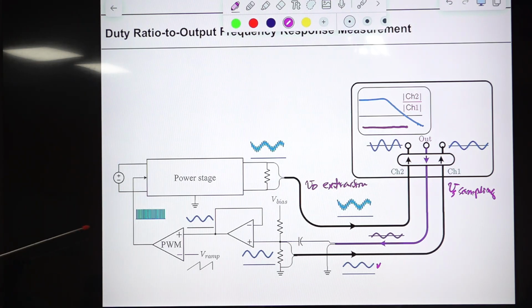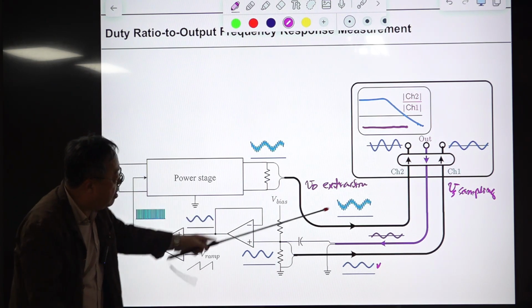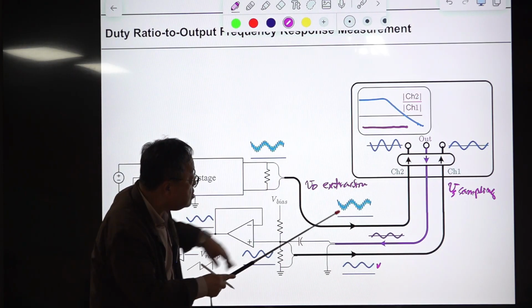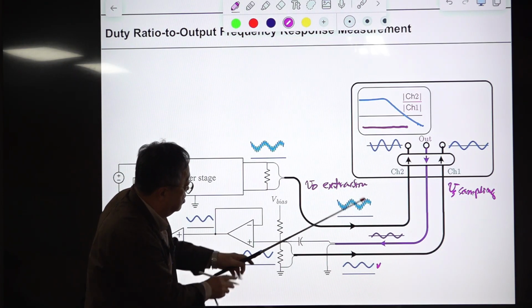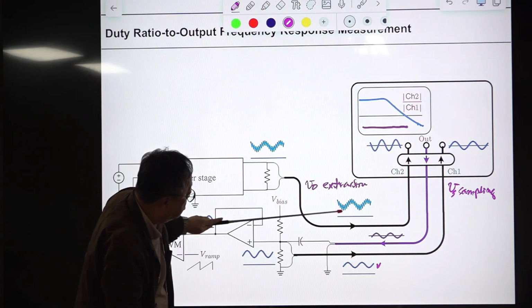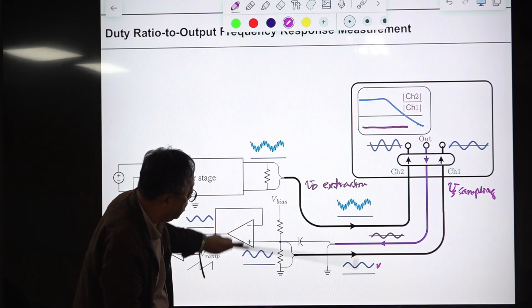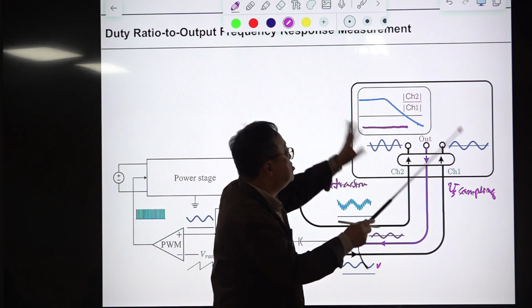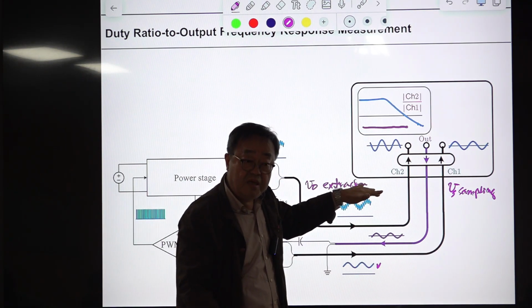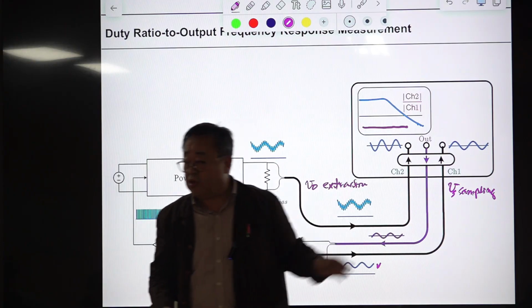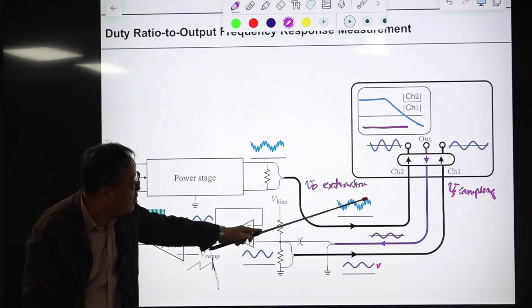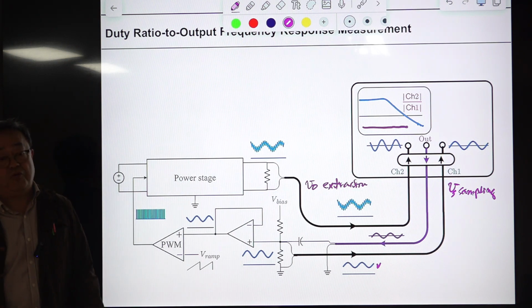Okay, so every signal has 3 different components passing through this. Because there is a DC component, a different component, and the sinusoidal component. The same is true here, and the signal goes there, and this equipment is processing this, just getting rid of the DC component and extracting the sinusoidal component here using some FFT algorithm.